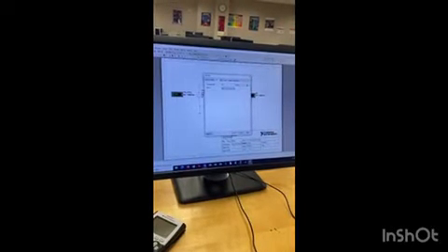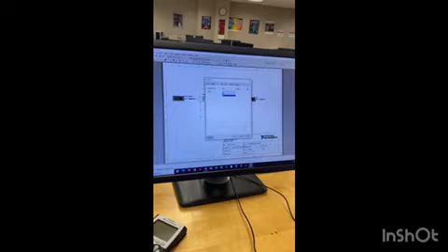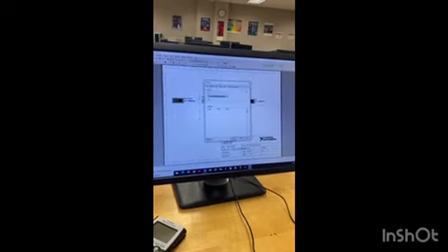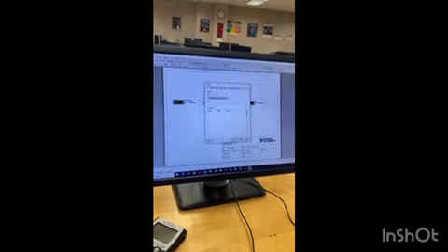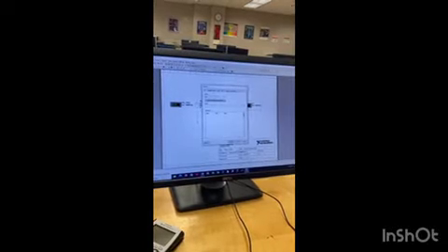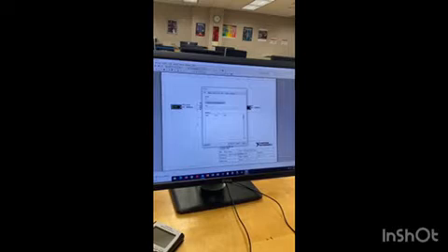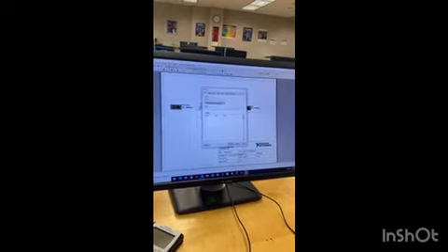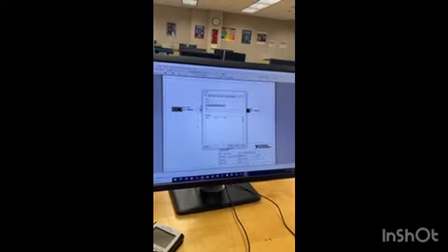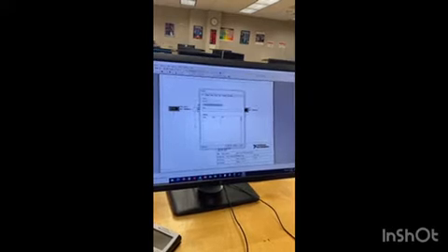And then on our second voltmeter, we're going to change the mode from DC to AC. And we're going to change the ref des to V2 underscore RMS. We're going to click OK.